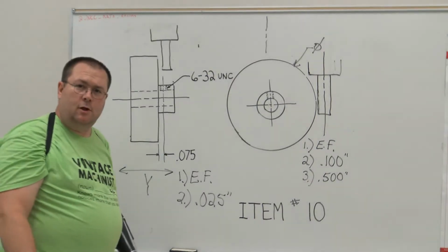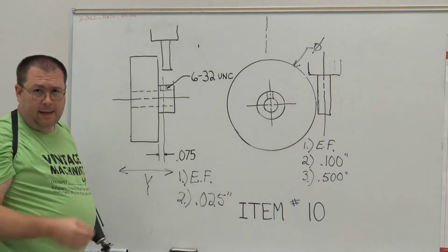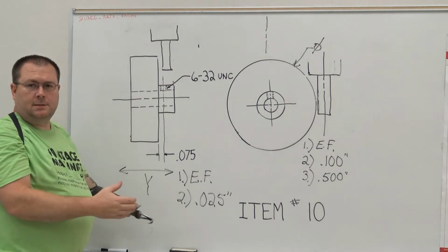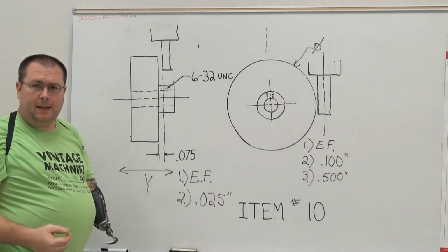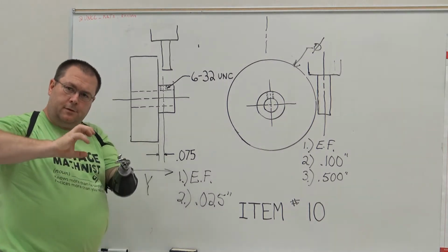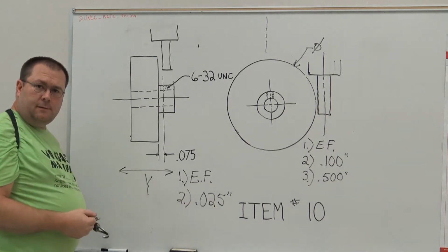The answer is absolutely not, because we have to start dealing with backlash. Backlash is a big problem. You guys have already been taught about backlash, but it's the slop or clearance between the nut and the screw that drive that axis to position.